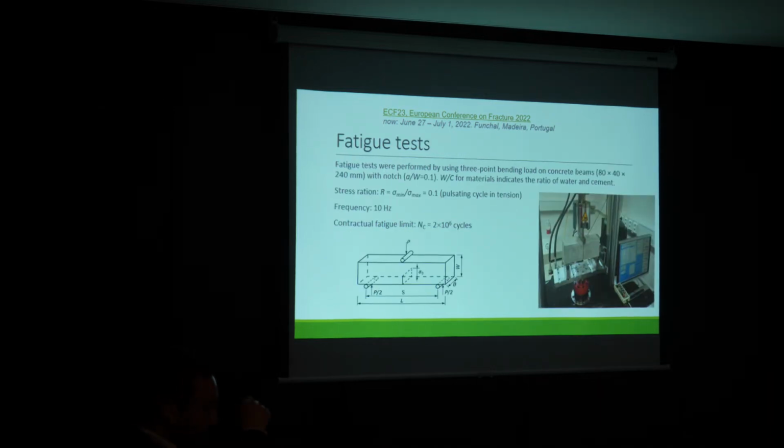Here you can see the fatigue test, how we perform it. For concrete, it is important to use a 3-point bending test because it is a typical bridge part, and it is under tension together with compression, and the bottom part is loaded by tension. The cracks propagate inside. For easy evaluation of the position of the vertical crack, we prepare a small, very short notch.